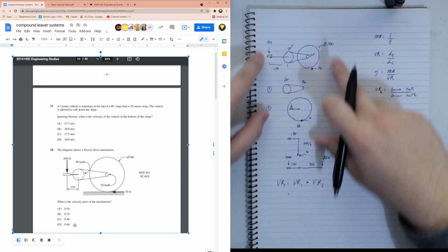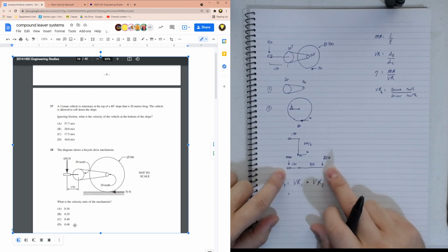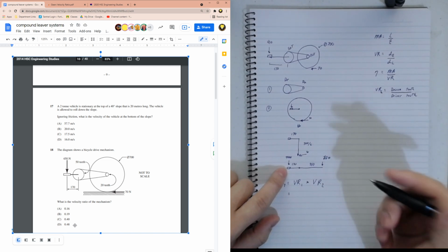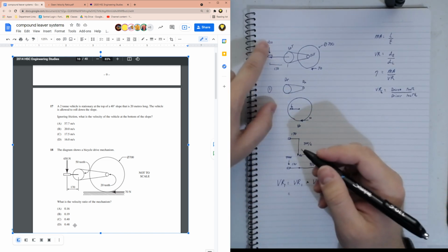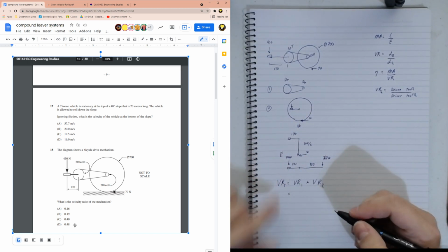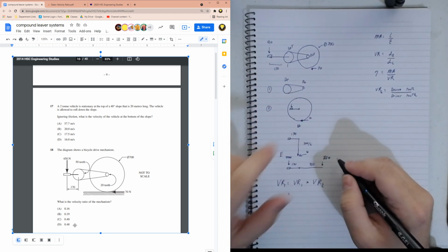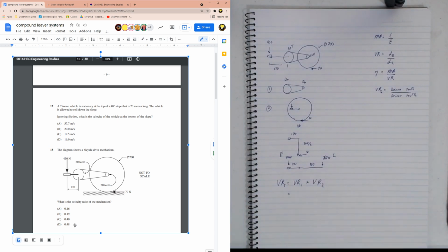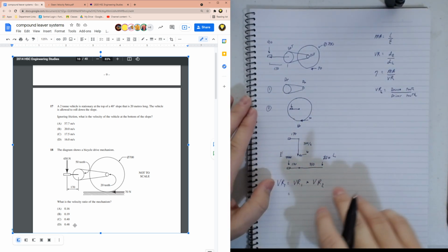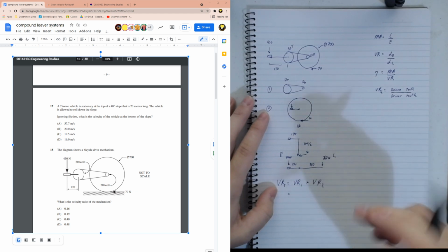When we look at this larger example, this lever over here, we can find out which one is the effort and the load, or we can just define it as E and L. Effort is where you're putting your pedal in, so everything on the pedal side is going to be our effort, and everything where our 70 Newton is, or where the tire touches the ground, is going to be our load. That means we can start to write out our formulas here.